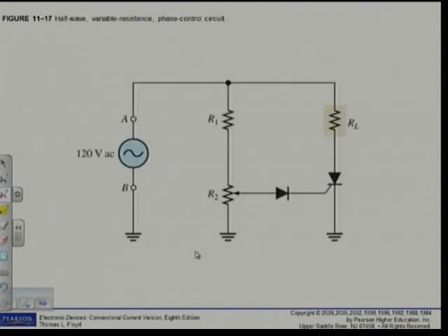The next circuit, that is on page 563, half wave power control. Now where do we use circuits like that? Sometimes you got light dimmer circuits. They don't use SCRs, but they use triacs to dim the intensity of a light. We can use it there. Speed controls in these small drilling machines, there they won't also use a SCR, they will rather use a triac to do the job. But now we're going to look at this half wave power control.